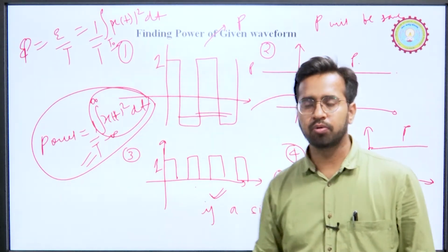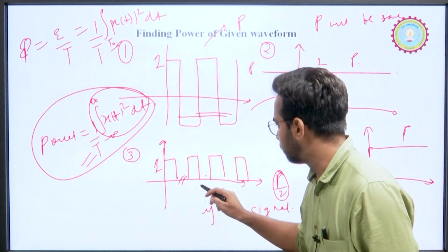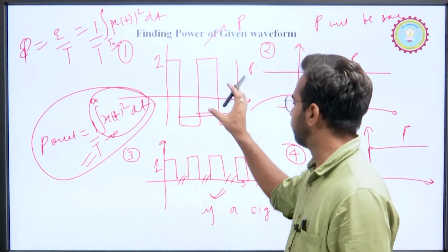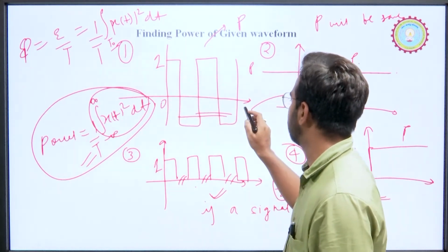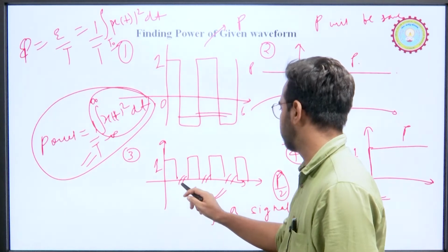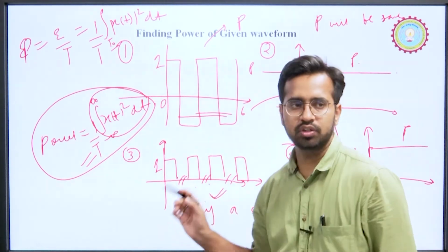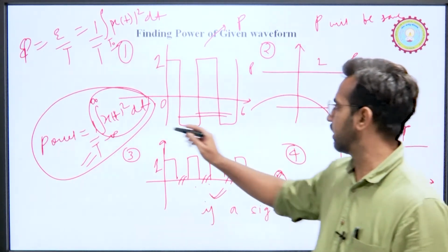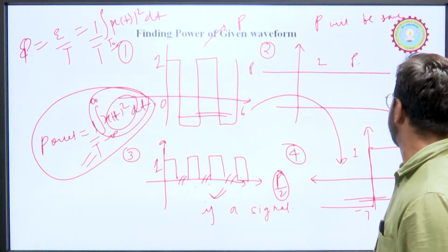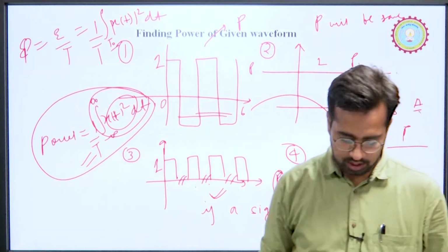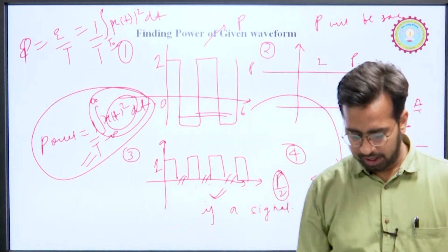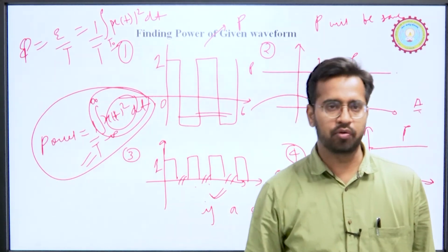It is P by 2, because see there is 0 signal for negative time, there is 0 signal for half the duration. This signal exists from 0 to suppose 6, then from half time, that is from this 3 duration, it has 0 signal. So, the x(t) square value will get reduced. So, power will become 1 by 2, that is power will become half. Also, power calculation is also independent of time shifting, time scaling, amplitude reversal.